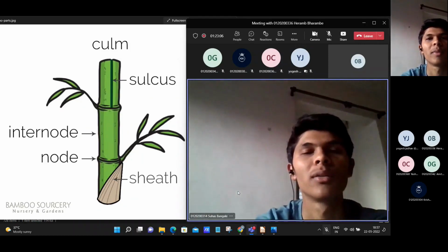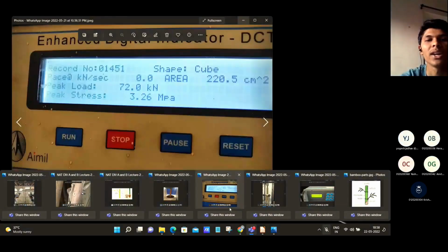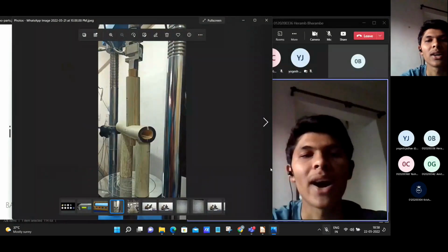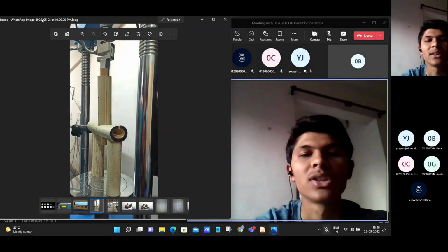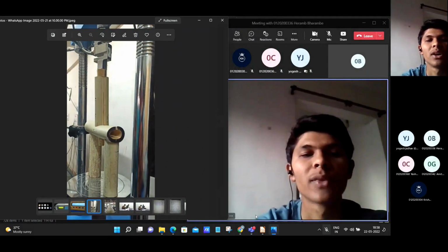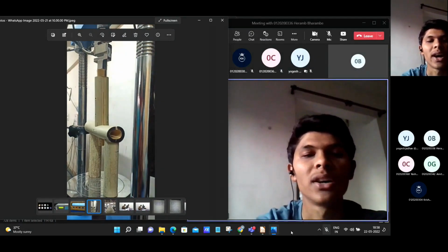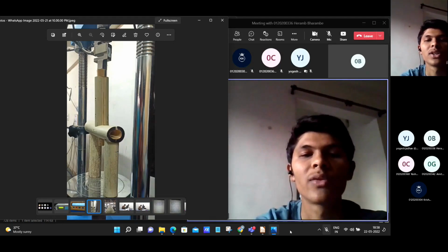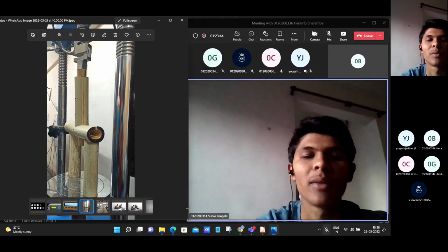tests. As we want the whole dimension as an assembly vertically, we calculate it by considering the diameter of two supporting bamboos and also by considering the fish mouth cut. So the slant truss we cut by using the hypotenuse rule and other parts by using basic geometry. Then we divided the figure of the truss into equal portions, and then we calculated the force in individual members by using the method of joints and method of sections.